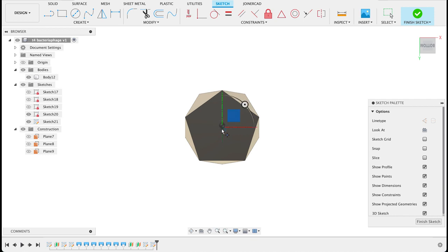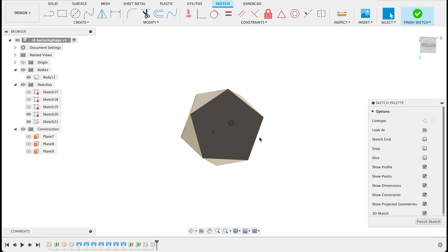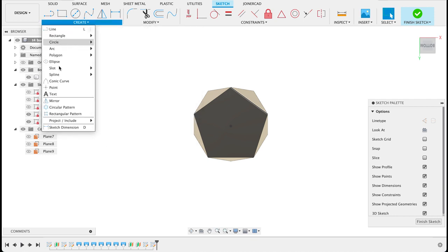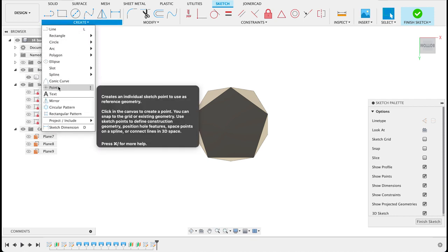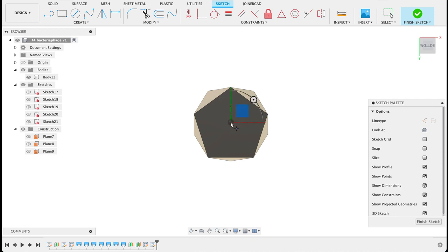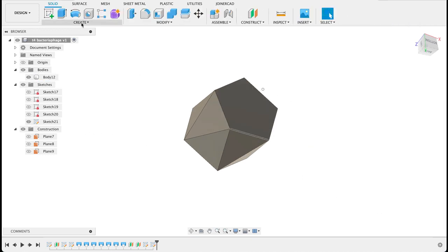It's not really letting me do it. Now, 2 points there. I'm wanting this to snap to the origin, but it seems to be snapping to the point on the top one. It should be in line, but they aren't really. I think I've gone a bit off here. So now once you finish sketch, you can just go create loft, and you'll loft from the surface to the point.